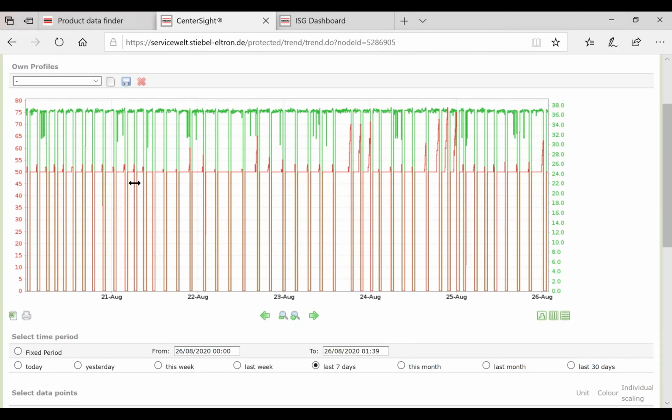I get on almost a daily basis contractors arguing with me, telling me I'm wrong, that the pump is running and there's flow, and I very confidently and calmly tell them that they're wrong, that we can see the water flow rate. There is no water flow rate, therefore they have no flow between their heat pump and their buffer tank. In this case, you can see we're getting over 37 liters per minute.